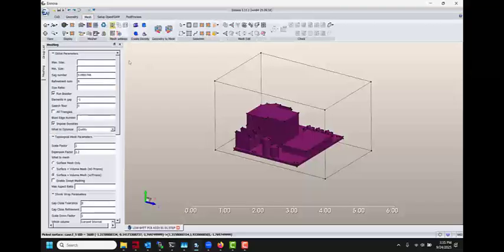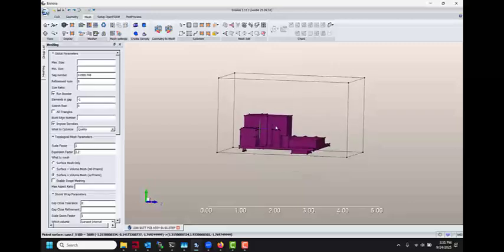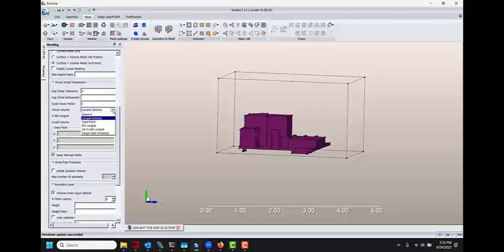So the way we do that, this model looks like it's in inches. I'm going to say my maximum size mesh is 0.2 inches. My minimum size mesh, I'm just going to allow it to go to 0.02. Leave the surface refinement the way it is. I'm going to be doing a shrink wrap and go first n. And although there are some small components in there, I'm just going to look for the top 15 components.